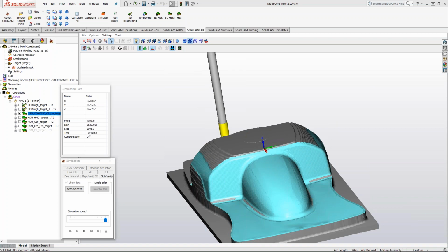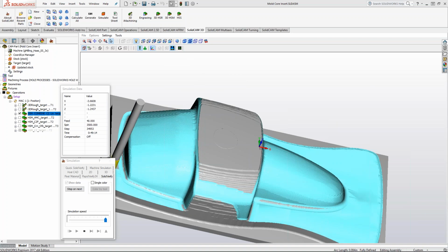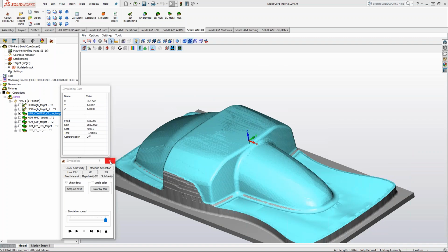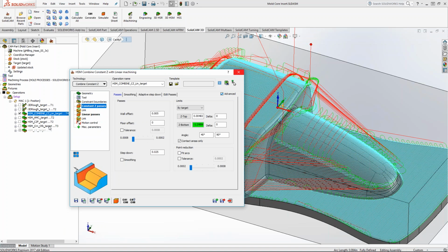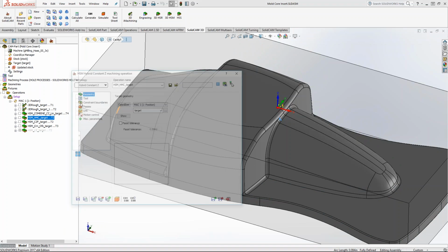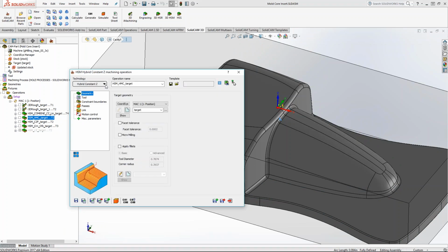Yeah, guys, one thing I really like about this toolpath is, like Scott was just showing you guys, he's got from 0 to 40 degrees set up, or 0 to 50 degrees, I can't remember what you had. Yeah, 0 to 45, and then from 40 to 90. So you get that nice little overlap in there as it's coming to it. Now, you can do an exact end and stop right at 45 degrees, but there's that possibility of getting that little line going through there, so it's always nice to have just a little bit of an overlap there.